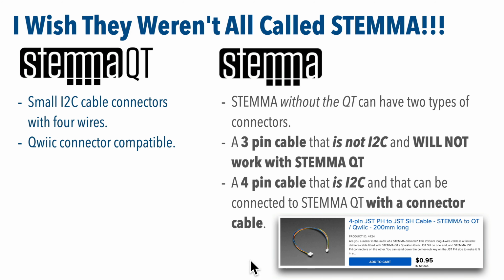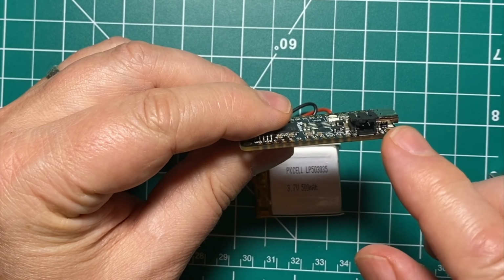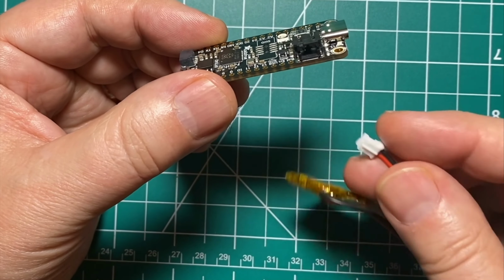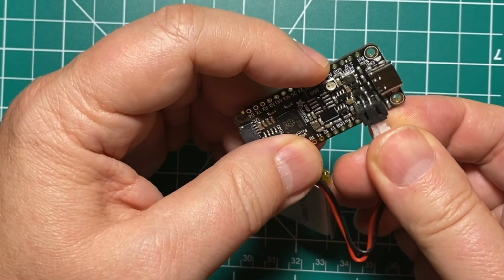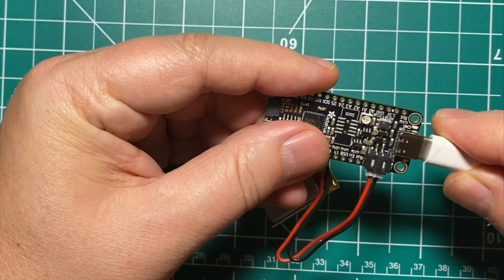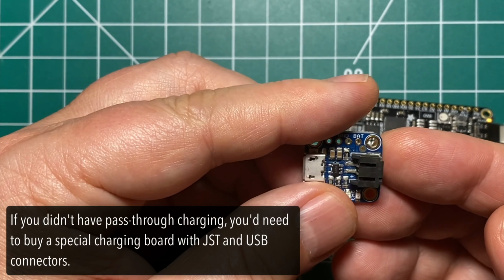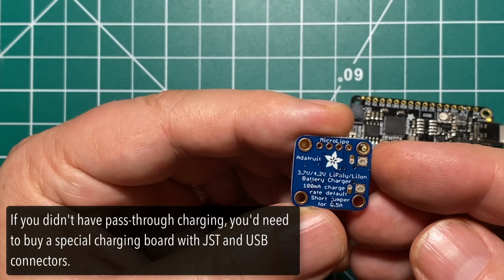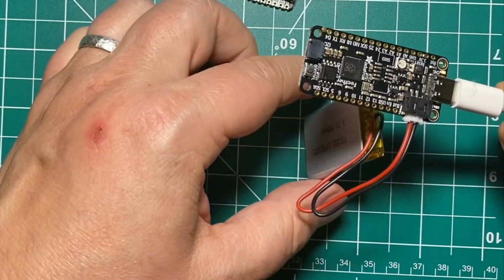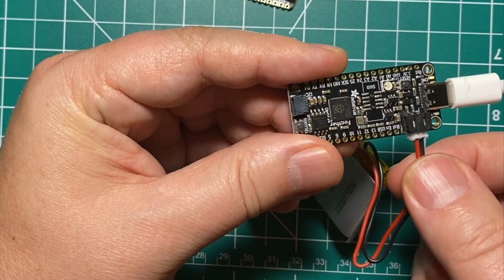Now, another reason why you might want to use the Feather RP2040 board is that it comes with a JST jack. This is the standard jack that's used for hooking devices up to rechargeable LiPo batteries, and even better, this jack provides pass-through charging, so if you plug the board in over USB, any LiPo battery that's plugged in will automatically recharge. Now, pass-through charging is convenient because it means that you don't need to buy a separate battery charging board. It's also nice because you can often plug a battery into your project, never worry about disconnecting it, and this is an advantage because JST connectors are sometimes tough to unplug, and it's really easy to accidentally break off these wires.